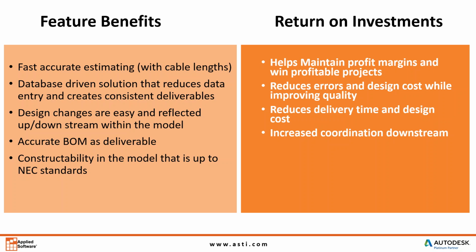Constructability in the model that is up to NEC standards. It's going to do those pull calculations, making sure that we can actually pull the cable through the conduit, that we're not damaging the cable. This is going to reduce time and rework, and it's got NEC standards in there as far as making sure that we're not too full in our conduit, and making sure that we've got not too many bends or anything like that in there as well.